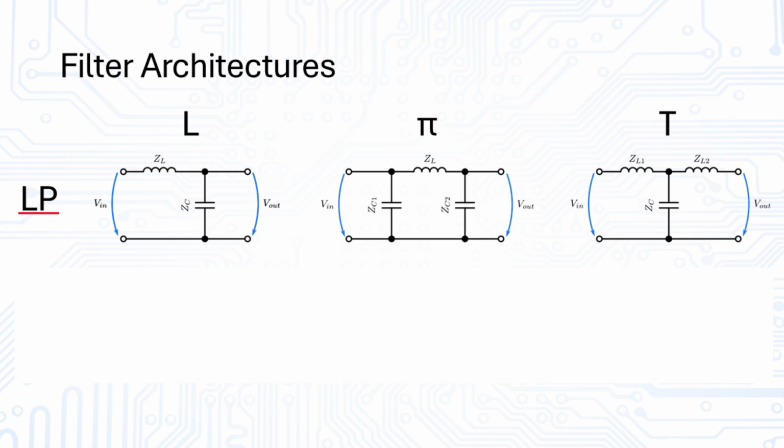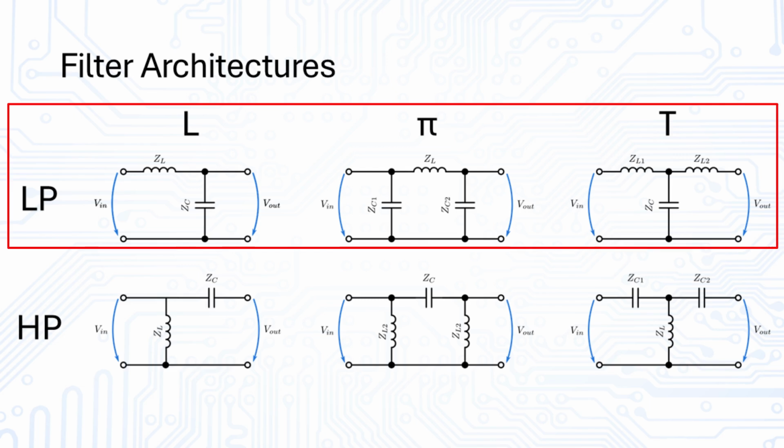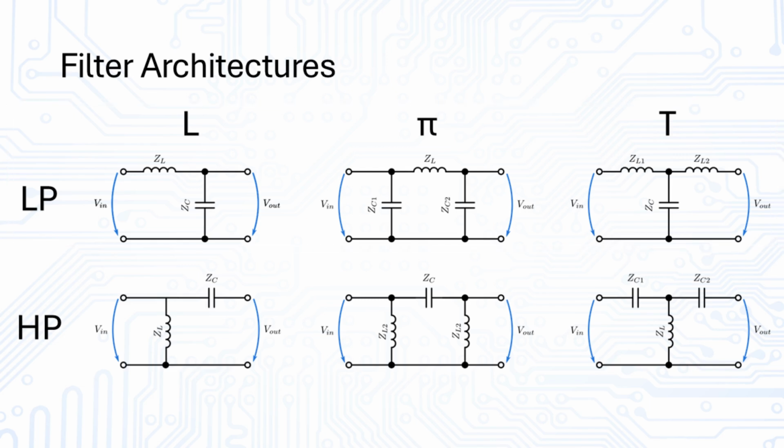The idea behind these low-pass filters is to create an impedance mismatch for high frequencies, which leads to a minimization of power transfer. By exchanging the inductors and capacitors with the opposing component, each architecture can be transformed into a high-pass filter. However, since we want to protect our power distribution network from high-frequency conducted emissions, we only consider low-pass filters. Also, note that we do not want to use a resistor in the high current path of these filters, as the dissipated power of such resistors in the power path would cause too much heating, resulting in losses.